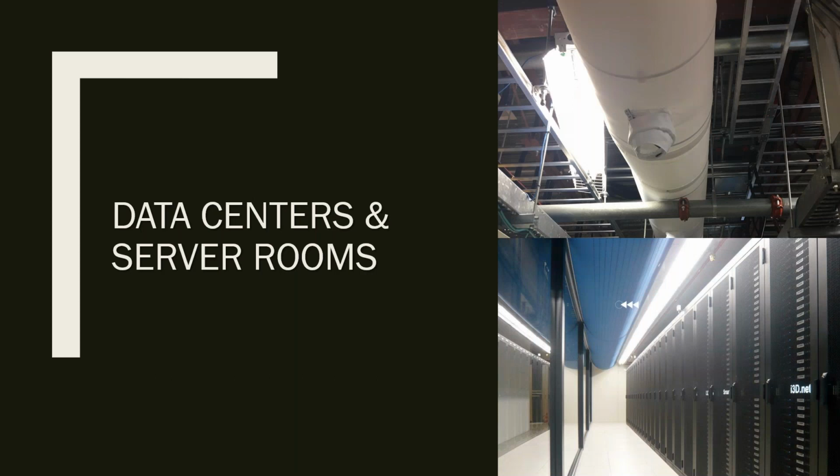We can also do data centers and server rooms. With data centers, if they want to remove hot air from hot aisles, that can be done with rectangular fabric duct under negative pressure. We can make those with nozzles and point those nozzles directly at the servers, directly at the equipment, to cool it down. They can also be made with dampers to shut off air from different aisles at different times where needed.